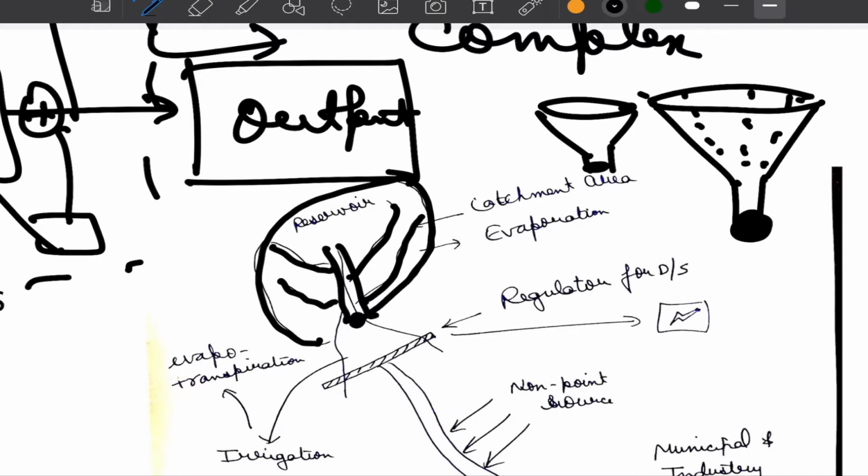And at the mouth, wherever the river flows at a particular point, from there we can always identify the extent of the catchment for that particular stream point where we are standing. So for example, if we stand at Sundarbans in West Bengal and try to do a backtracking, we will see that most of North India would be covered by the Ganga river basin. Similarly, when you stand at Haridwar or Rishikesh and you do a backtracking, you would see that the catchment upstream of Haridwar or Rishikesh would fall into the Ganga river watershed.